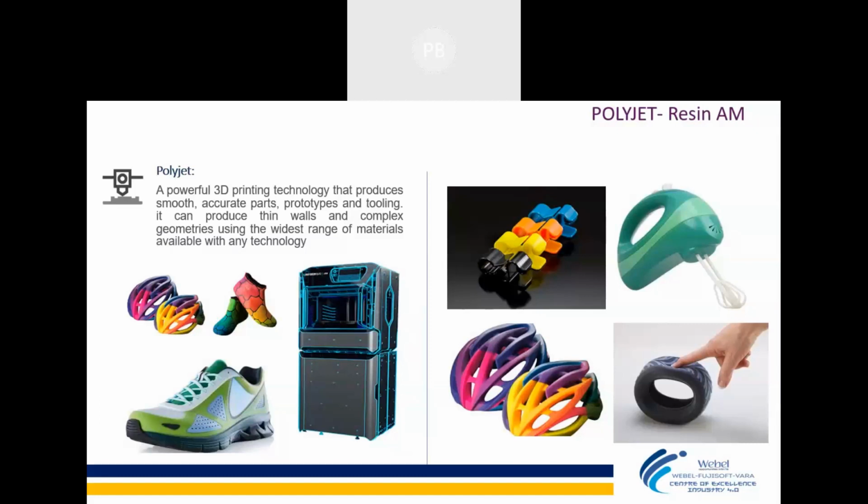So Polyjet is more used for color-based applications or aesthetic applications, where the end-use part can be directly made with Polyjet and shown to the customer, used for brand approvals, or used for marketing purposes. Polyjet is used for the final iteration of the model or for different color segments. And yes, Polyjet also plays a major role in the medical industry. We'll discuss how Polyjet is useful in medical, and with different machines we'll show you the different uses.